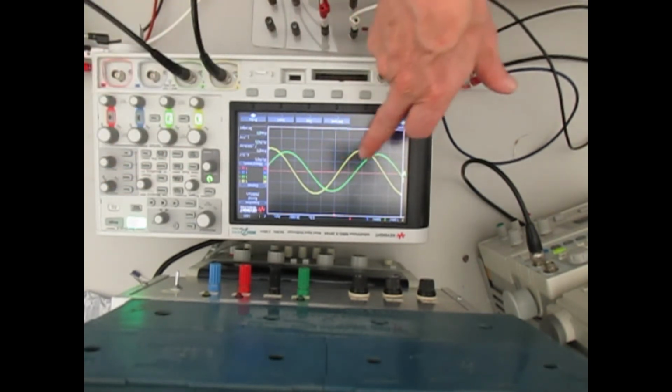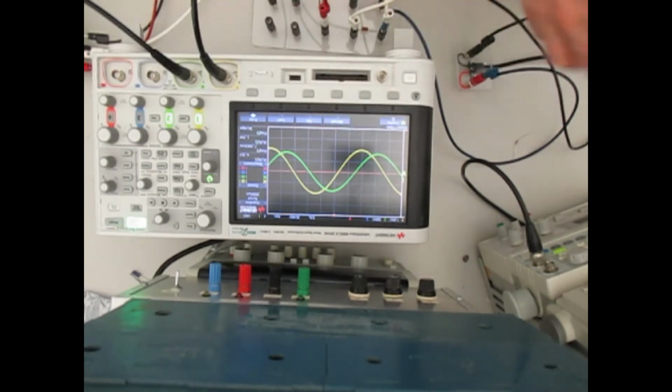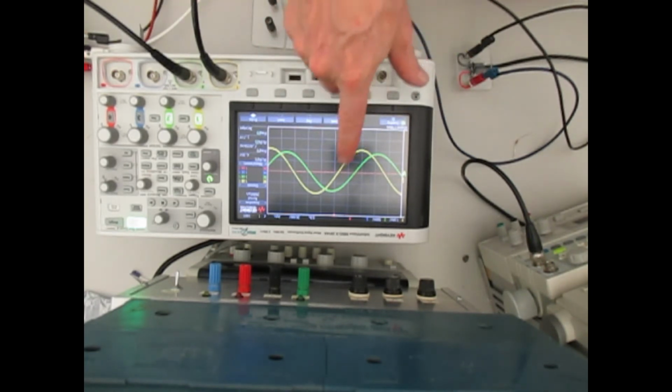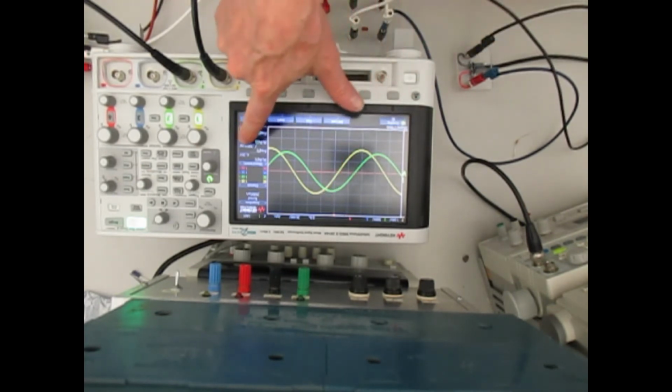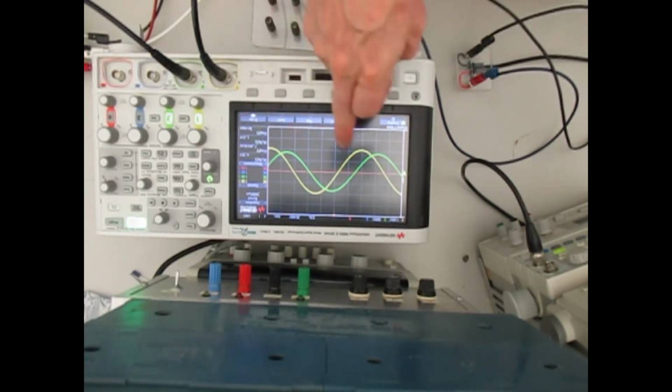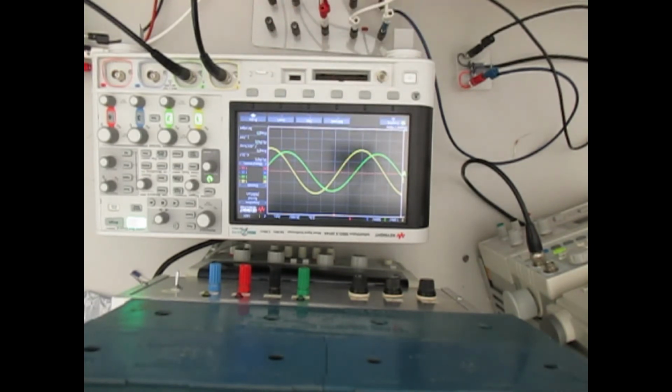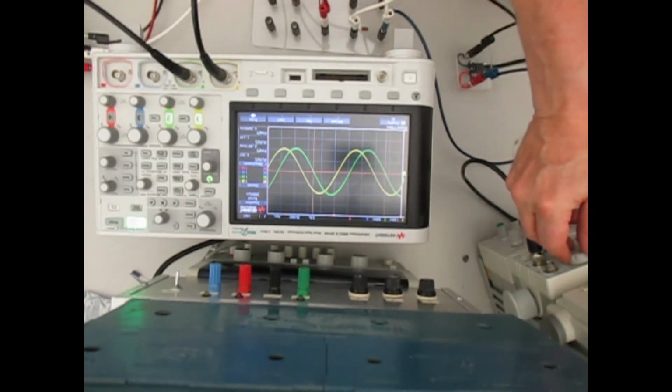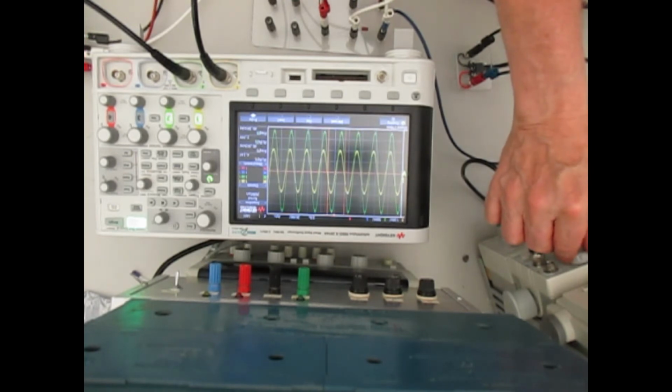But you can see now the phase shift is changing. Right now I'm at 7.4 kilohertz. And what I need to do is finally get up to 50 kilohertz. And by that time, these two waveforms should be right on top of each other. See, actually, right now at 7.4 kilohertz, my peak-to-peak voltage on my input is 4.3, and my peak-to-peak on my VR is 1.79. And again, these are just going by what I've got on right now. So let's crank our way up here.